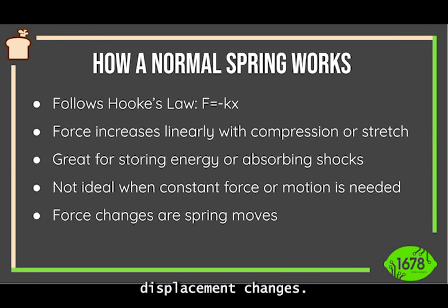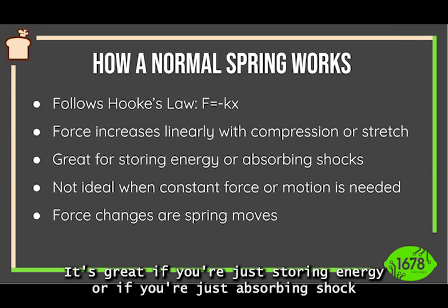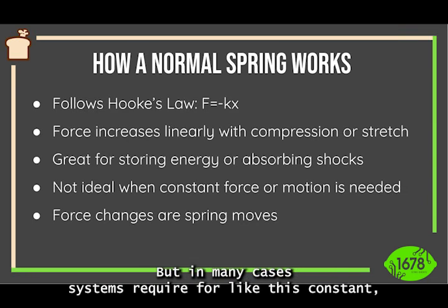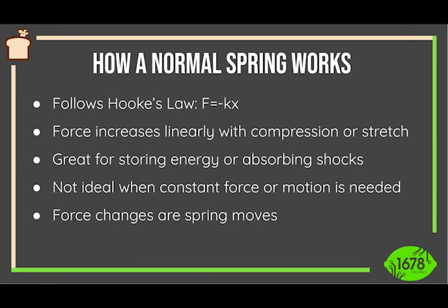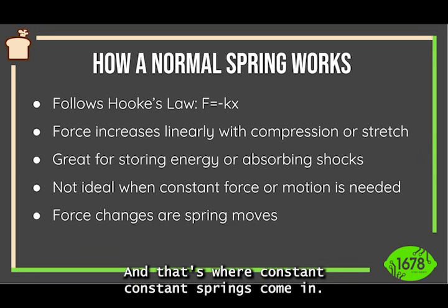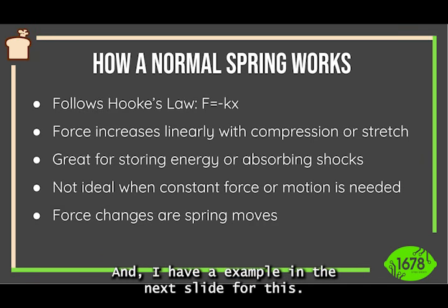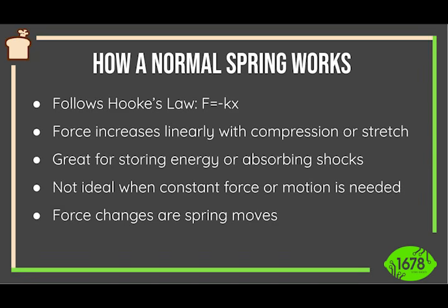And this non-constant force is great if you're just storing energy or if you're just absorbing shock, and if it's not catered for a specific geometry. But in many cases, systems require a constant spring force, and that's where constant springs come in. What they help do is more smoothly lift, per se, arms. And I have an example in the next slide for this.